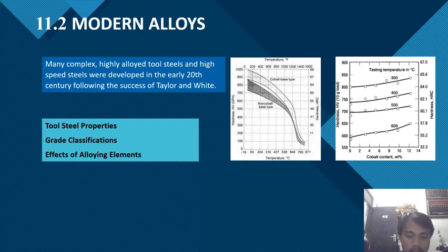Manganese contributes to hardenability, but concentrations are generally not high in high speed or tool steel because a relatively minor increase in these alloying elements markedly increases the brittleness of the steel and the danger of cracking upon quenching. Phosphorus has no known beneficial effect on any of the primary properties of high speed and tool steel, and is normally present as a tramp element in the scrap that is used to produce this steel.